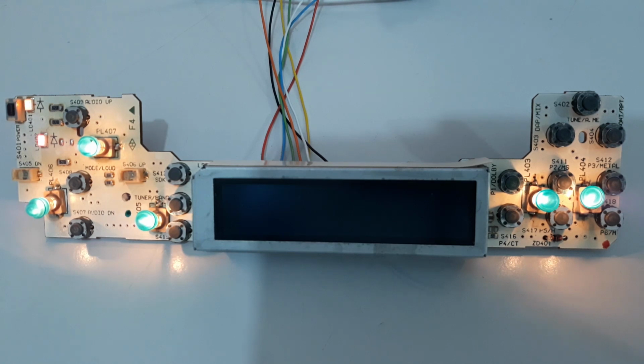As for the power supplies, we have two. One for plus 12 volts DC used in the bulbs of the backlight, and the other is a value above 5 volts, perhaps close to 9 volts DC, to feed a circuit made of R limit that is associated with a 5 volts zener to provide the plus 5 volts to power up the IC, and at the same time the backlight of the LCD itself.